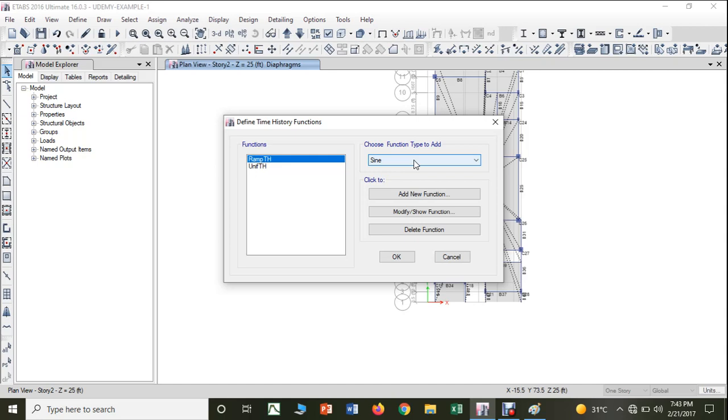So when you have a very high significance of those structures, definitely we cannot do just a static loading, we have to do the dynamic loading. And along with that, definitely we have to consider the soil as well as the building together, and we are supposed to do soil structure interaction design.